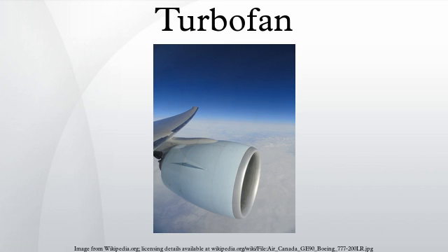The engine produces thrust through a combination of these two portions working in concert. Engines that use more jet thrust relative to fan thrust are known as low bypass turbofans. Conversely, those that have considerably more fan thrust than jet thrust are known as high bypass. Most commercial aviation jet engines in use today are of the high bypass type, and most modern military fighter engines are low bypass. Afterburners are not used on high bypass turbofan engines but may be used on either low bypass turbofan or turbojet engines.